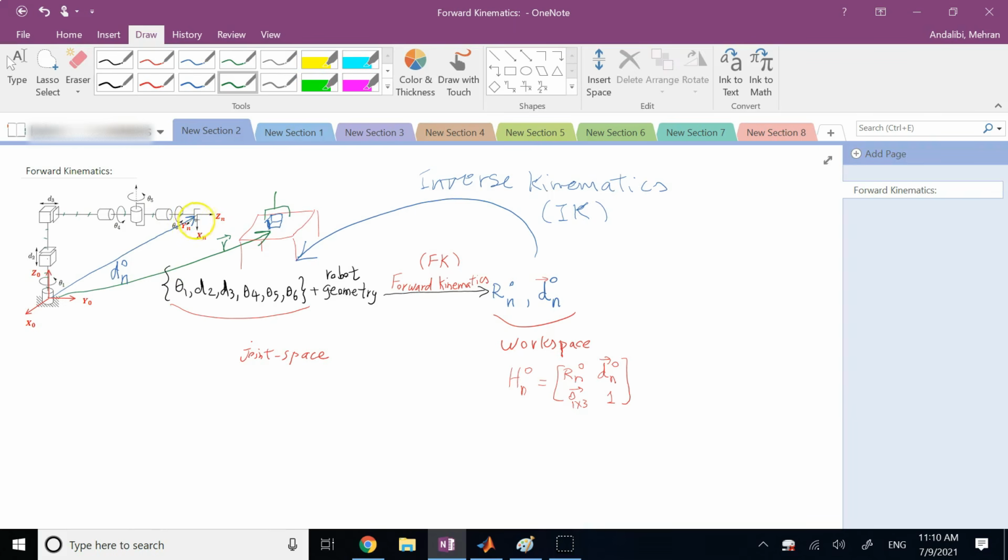Okay? So it's not always just the end effector that matters, where it is and what orientation it has. Sometimes you have to care about the position of the rest of the points of the robot. These are important as well to avoid collision, because not always is everything around the robot clean and free. Many robots sometimes have to work synchronously together at the same time, and they are close, and when they fully extend, they might hit each other. So forward kinematics allows us to avoid collision as well, knowing where every point on the robot is, including the end effector. The equations are typically very nonlinear.